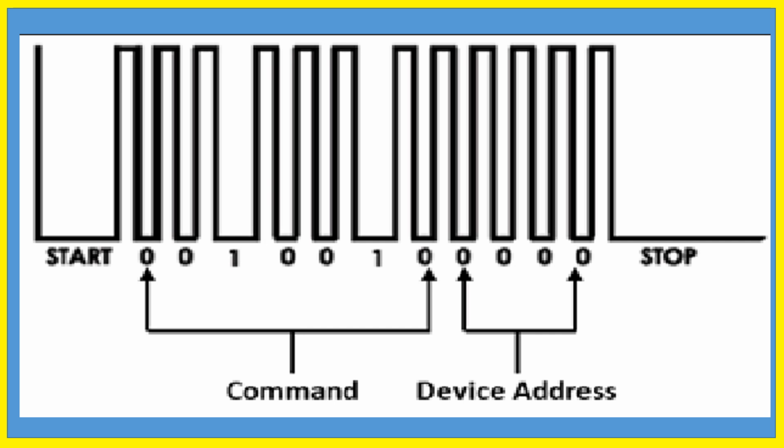Lastly they have given the device address, which RTU, which switching post, and lastly they put 0 volt for a longer time as the stop. So this is one set. This wave they will mix with the carrier wave and then send it through the communicating cable to the RTU.